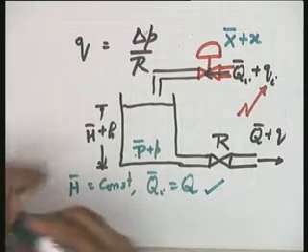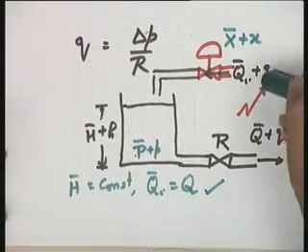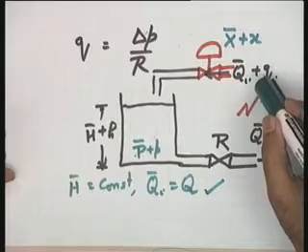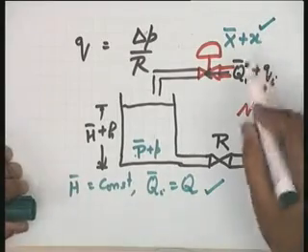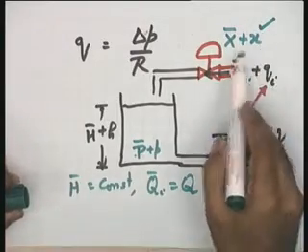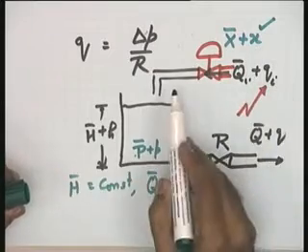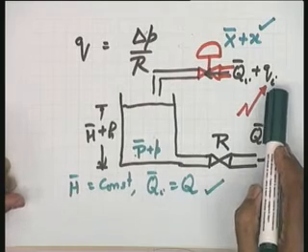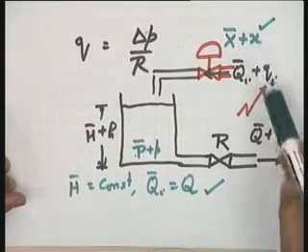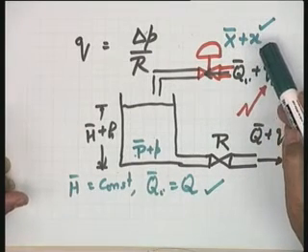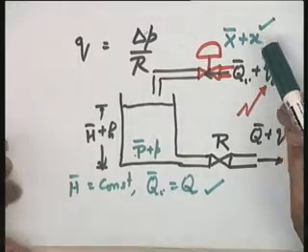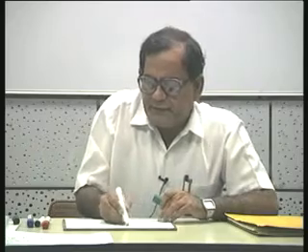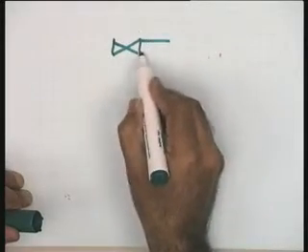Now, let us say some disturbance occurs, or let me assume that I myself disturb the system by changing the inlet flow, and that change is captured by this variable x. So, if I change this x, naturally Q I will change. So, in this particular case, please see, your Q I variable has to be a function of x. I hope you will agree with me that if I have a valve of this nature,